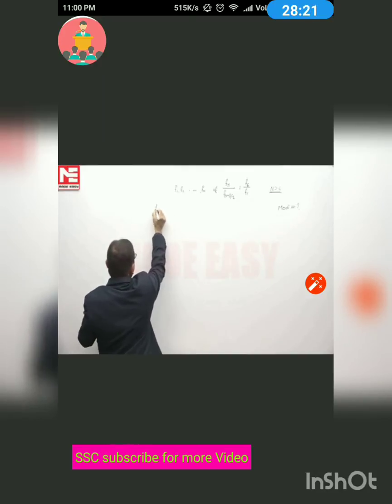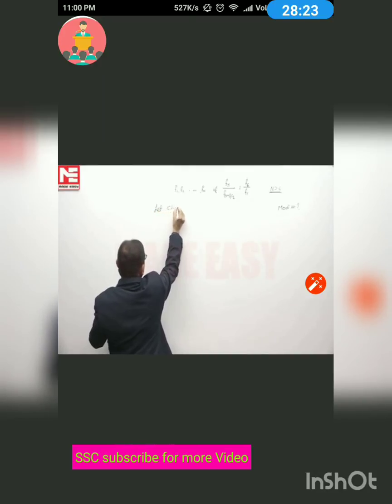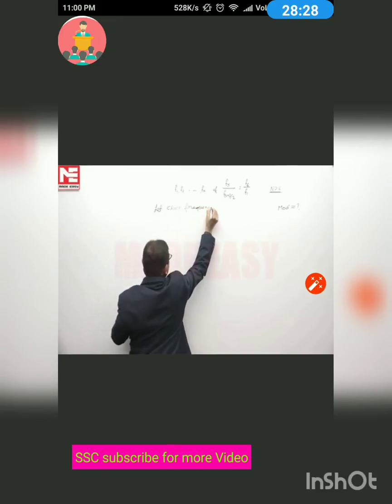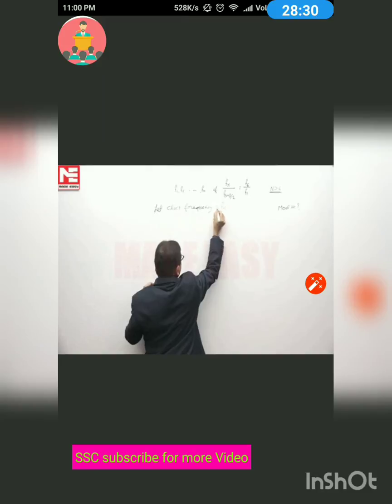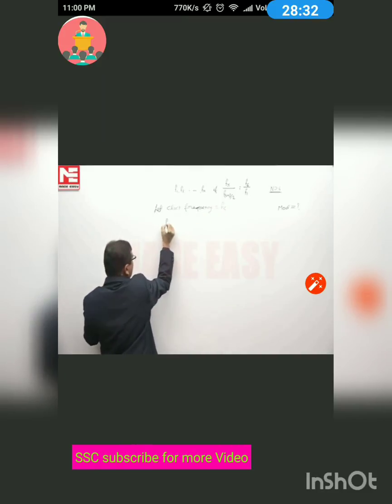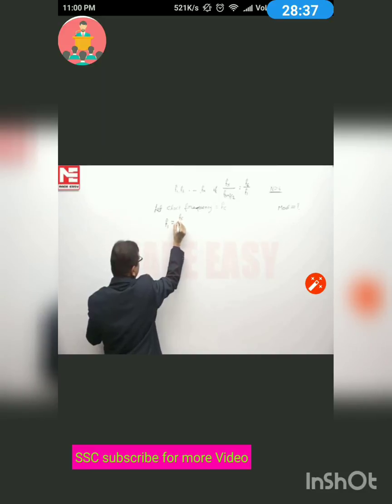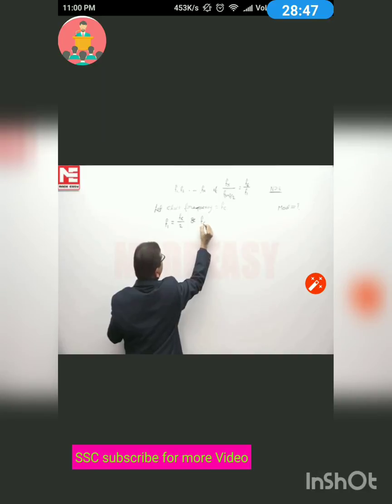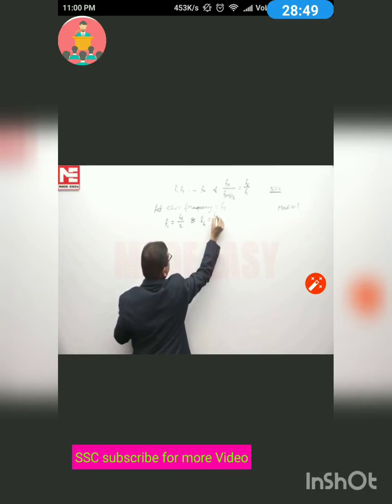Let's consider the clock frequency which is used on this counter is Fc. So the frequency of the first flip-flop is Fc by 2, and the frequency of the sixth flip-flop is F6, which is Fc divided by 2 to the power of 6.